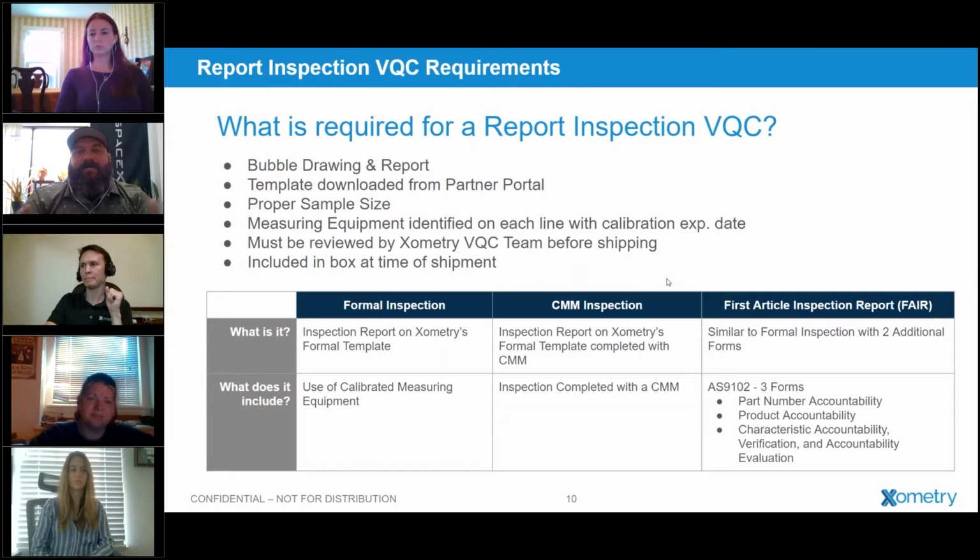And then when you fill in those boxes that are required, it'll turn white, right? And so that'll make life a little bit easier on everybody to know what boxes have to be filled in, what boxes don't have to be filled in, that type of thing. And then, as far as the CMM goes, that is translated onto the formal inspection report, whether it's an AS9102 form or the formal inspection form. We do need that information dumped in.